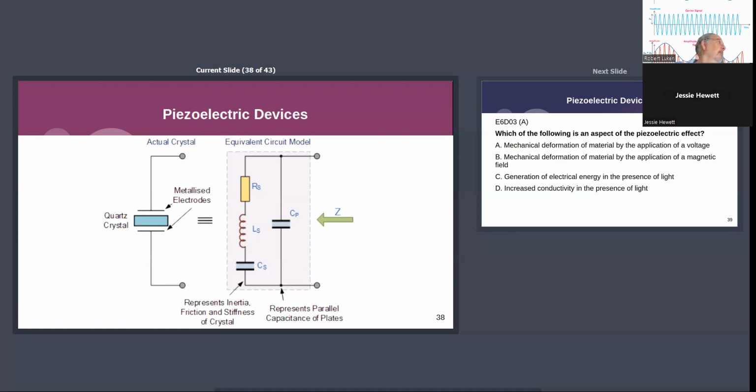Where does temperature get represented in these? We all know if you take a crystal and put it in an oven, it's going to be more stable if you control the temperature. But there is no accounting for that in your schematics. Well, you're going to affect the capacitance, both series and parallel.